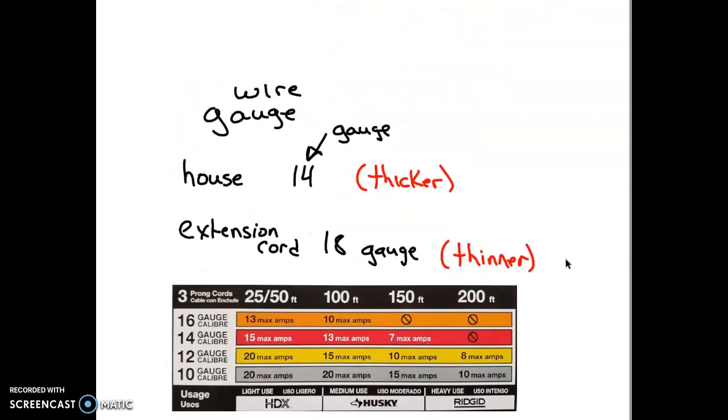This is a slide to give a quick explanation of cross-sectional area and resistance in some real-world applications. We're going to look at wire gauge, a term people use to measure the diameter of wire, but it's good to note that the wire gauge is not actually the measurement of the diameter. It's just a gauge, right? It determines the amount of electric current the wire can safely carry. And the smaller the gauge number, the thicker, or larger in diameter, the wire.